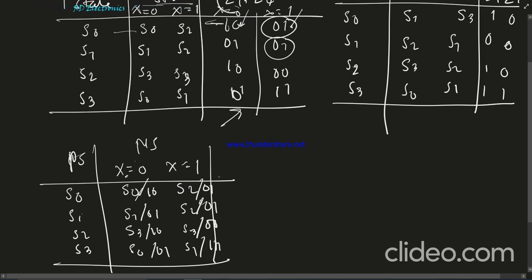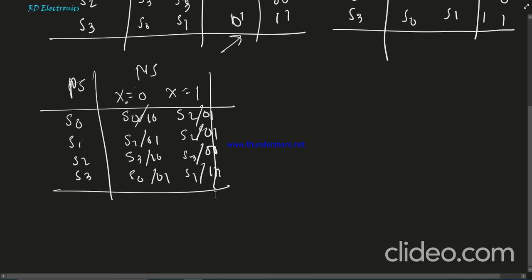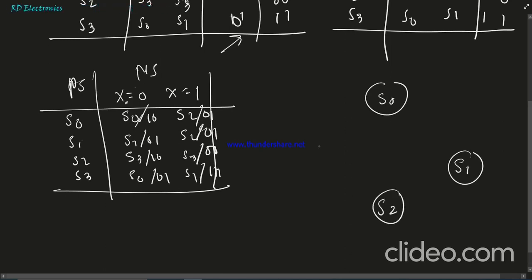So this is basically the reduced table approach, and this is also shown by another graph, known as the state graph or state transition graph. There are 4 states, and see that by this external input excitation, when x equal to 0, the transition is s0 to s0.